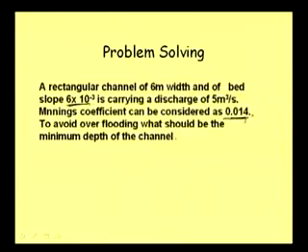Now, when the channel is in the real field, we have very little opportunity to change the bed slope, because if we need to change it we may have to do a lot of cutting in the ground, or sometimes a lot of filling up of the ground. Only then can we afford to change the bed slope to some extent. So generally the naturally available slope, depending on the topography of that particular area, decides these slopes.